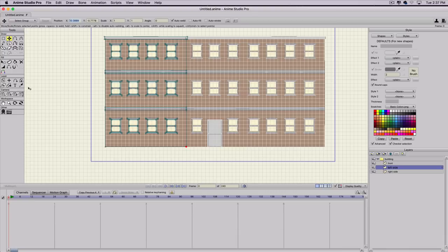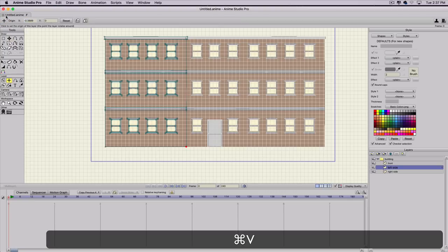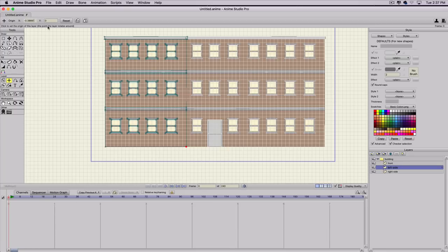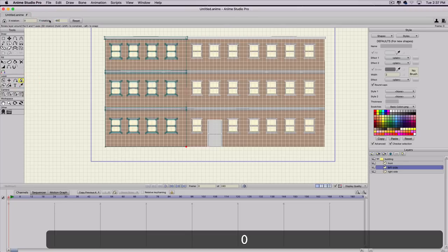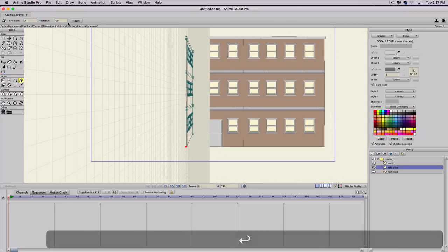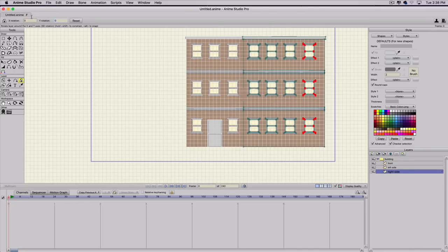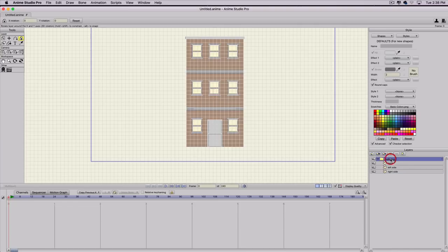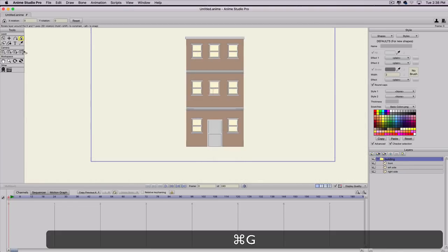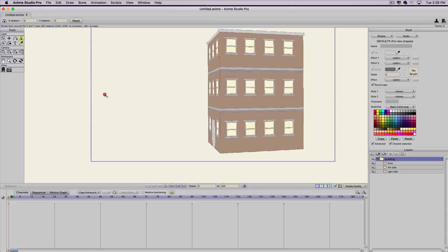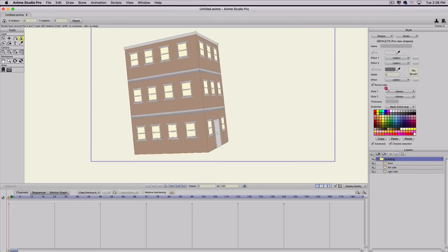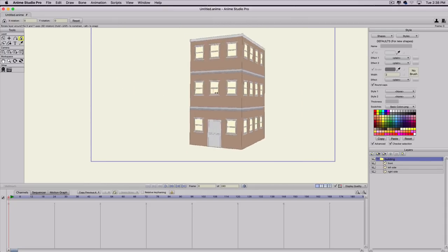Copy origin point. Negative 0.899, and then this, and rotate it negative 90 again. Okay, we'll go to the right side, make sure we rotate that 90 degrees, and then when we select the building, and then rotate it, now you can see we've got a longer building, and the sides are correct in their shape.